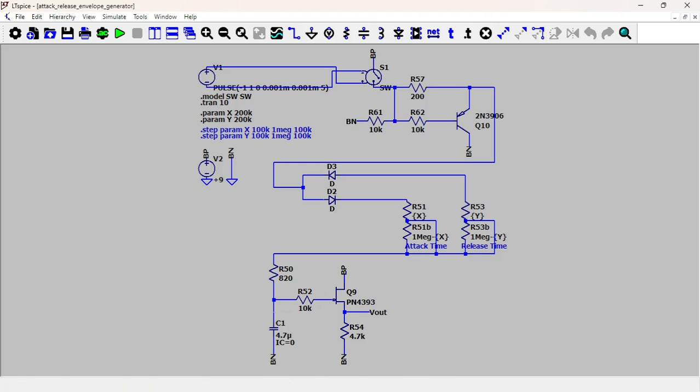Basically, it's to prevent C1 from discharging here. Because let's say that there was no JFET here, and the Vout was here. If the Vout is here and you connect something else like your voltage control amplifier, then the C1 is probably going to be able to discharge through that next module. That's why you have something with a very high input impedance here to prevent that from happening.